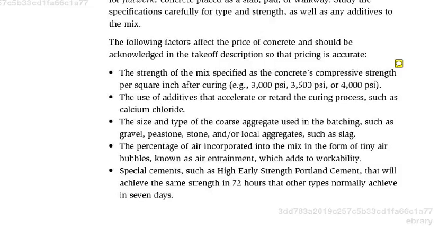Air, how much you have. If you're going to use an additive for air, again, you're going to break out separately. And also, if you're going to use different cements to make the concrete mix, you have to split it out based upon the cement. So when you do your takeoff, remember to break each different type of concrete out, label it with what type it is, and also have the units on it so we can see what you got.